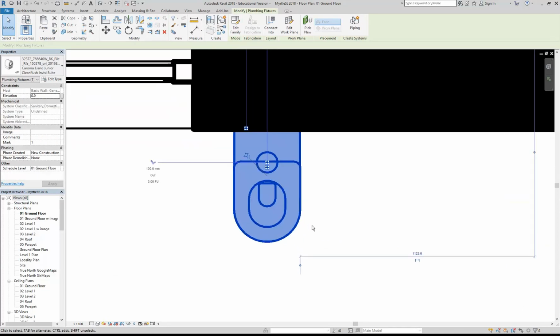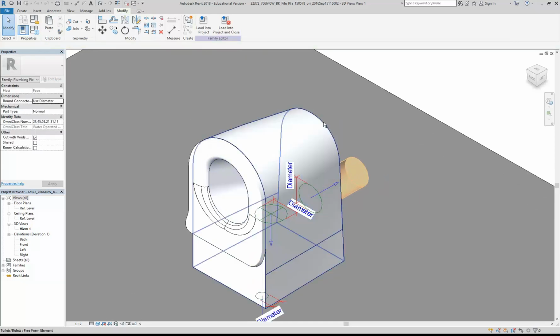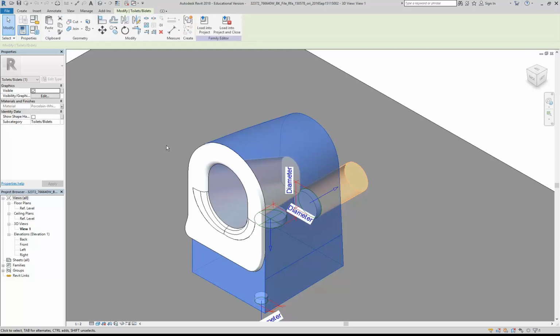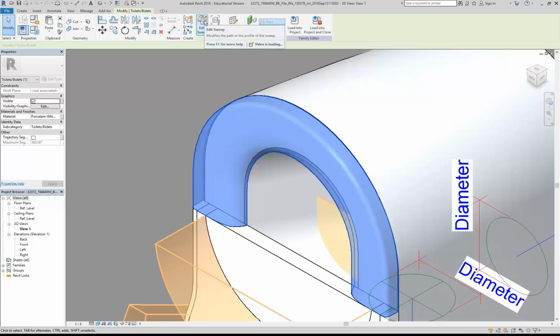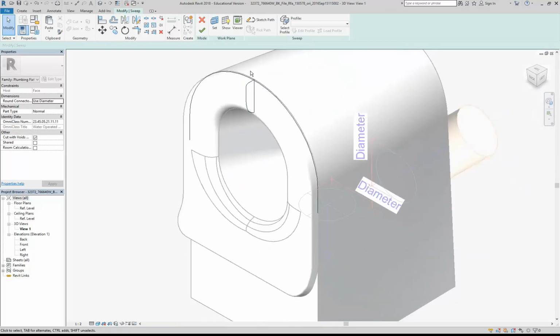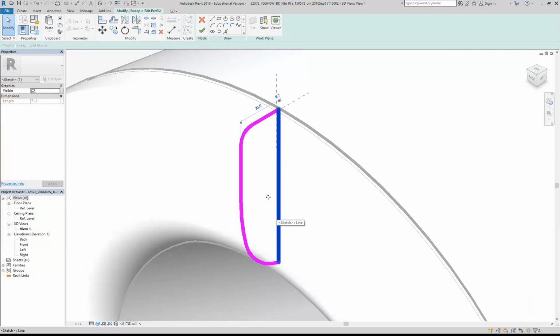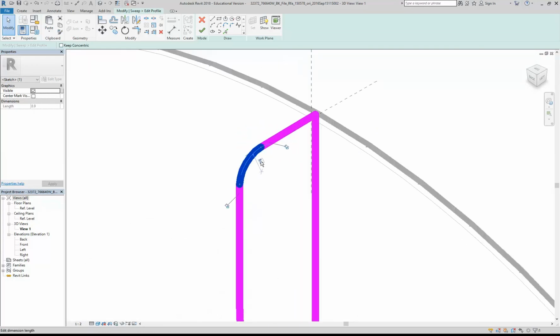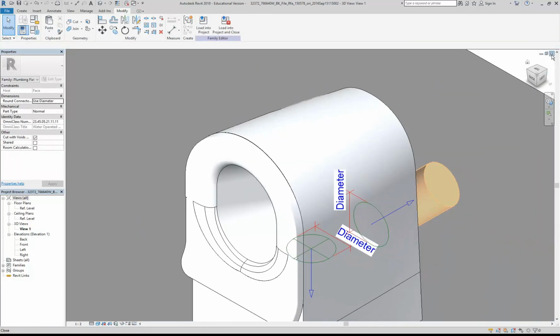But this one has more likely been made entirely using the Revit tools. And I'll know, again, if I select it, go to Edit Family, and then look at this. Oops. So you can see there, it's actually not giving me the right tools, so it's probably not the best example, but there we are, this one is. So you can see there, if I select that object, yeah, we know it's a sweep. And so you could change that potentially. A bit more involved than what we've been looking at, but just so you can see there, that is a collection of lines similar to what you would have drawn when you make your floors and roofs and ceilings and other things like that. So let's just maybe do a quick example. If I want to change the radius there, that's possible. Okay, so you've got all those options depending on how the family's been made.